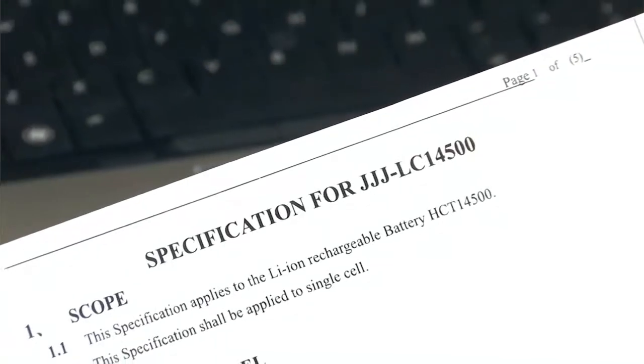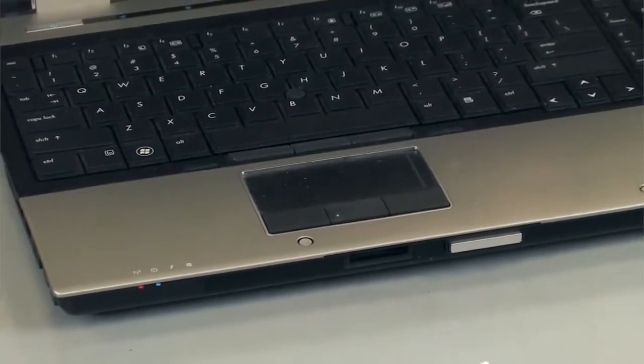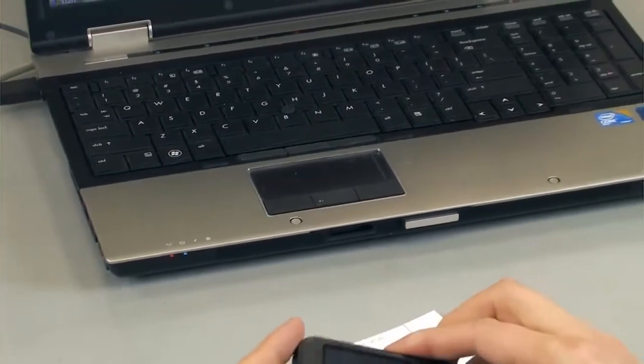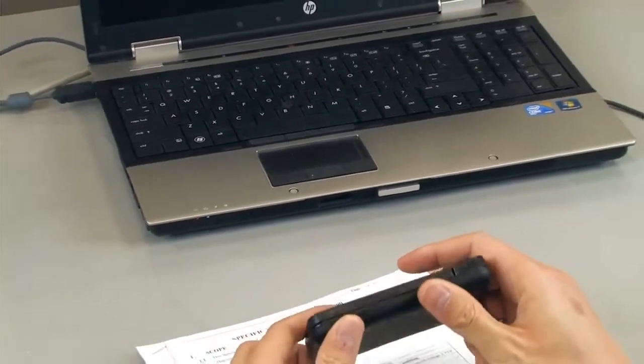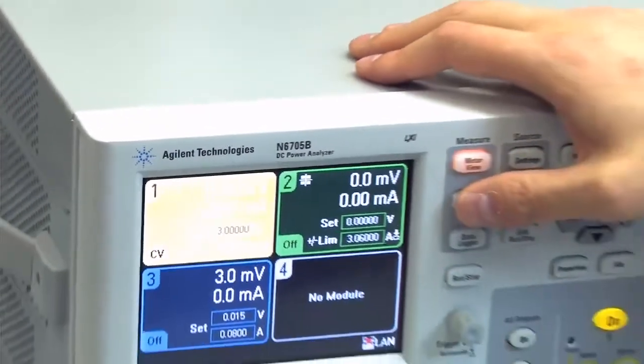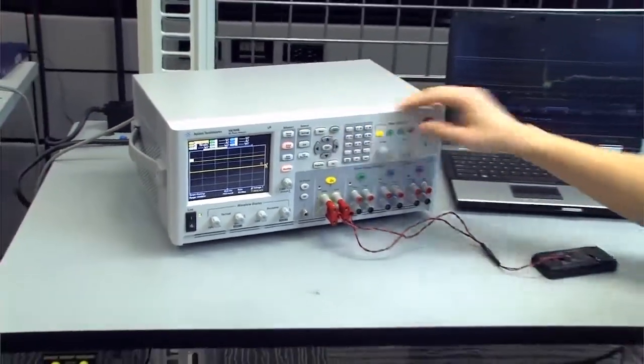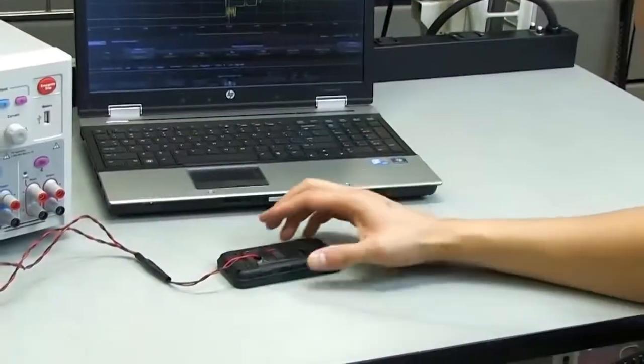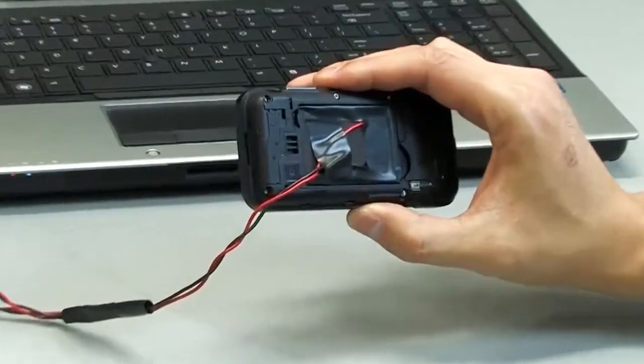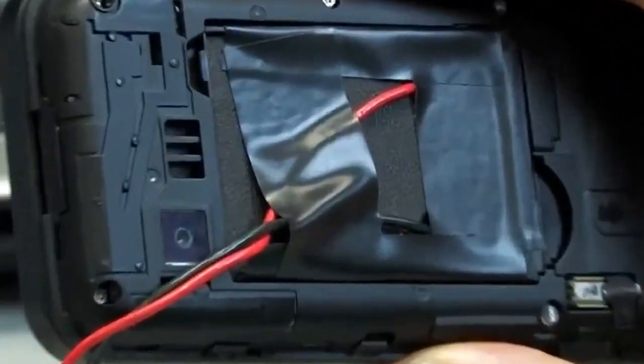Based on these results, findings include the delivered charge was 16% less than the capacity stated for the battery. The battery discharge termination voltage was higher than the target value. As you can see by this example, performing a battery rundown test yields unique and useful insights that complement the other test methods used in optimizing battery runtime on mobile wireless devices.